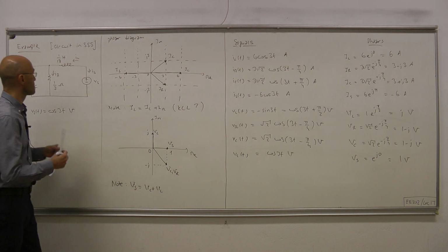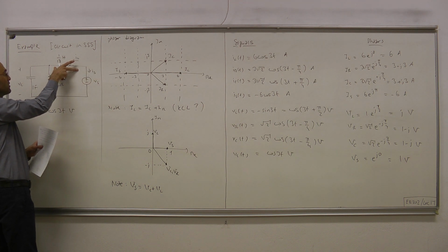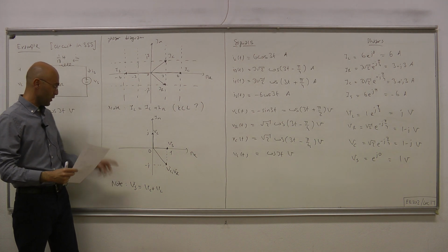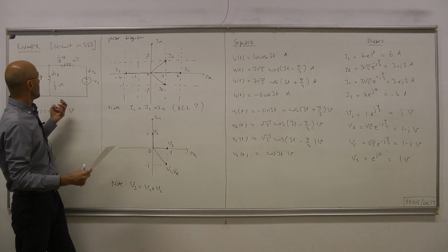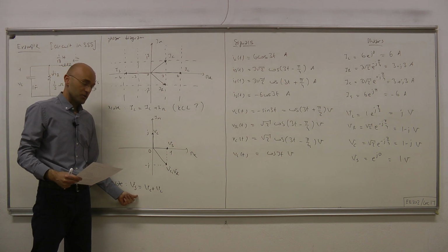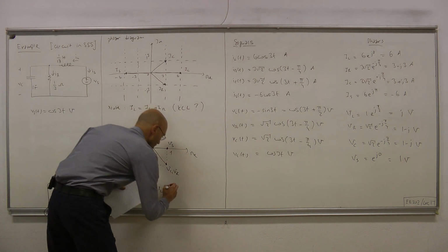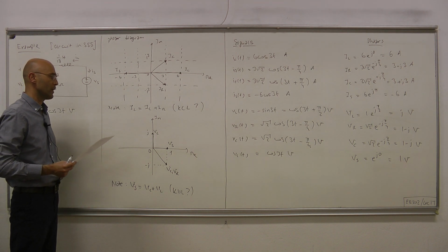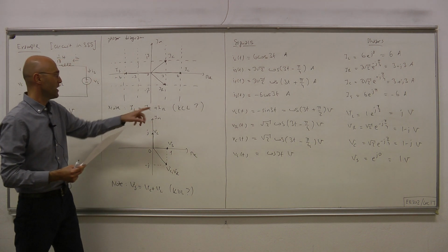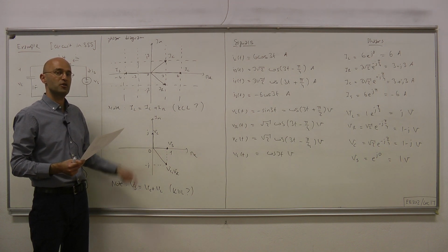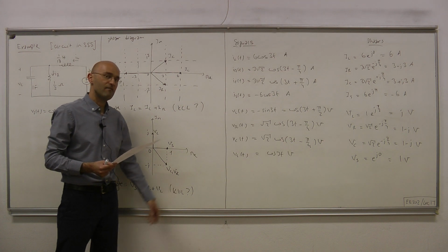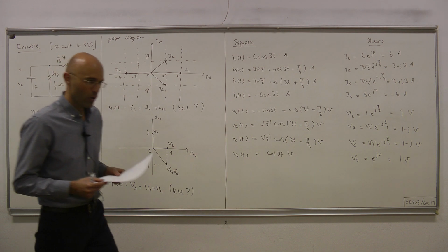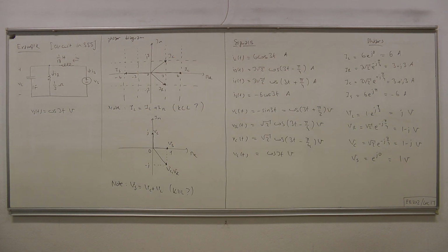Likewise, here, the voltage of the source equals the voltage of the inductor plus the voltage of the capacitor. We have the same equation also for the phasors: Vs equals VC plus VL. So that brings the question whether KVL holds in the phasor domain. And the answer is yes. So in other words, this is not just a coincidence for our special example, but we have KCL and KVL holding in the phasor domain in general. And let's quickly show that that is the case.